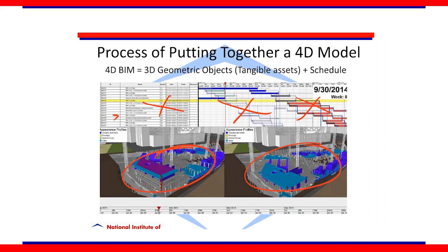So the way it is done is, if you have an item here, for example, let's say we're pouring foundation, sector A. What they do is they connect this particular line item into the sets of the 3D. So you technically click on this, basically whatever the columns and footings are linked to that particular line item, and you say link. So you keep doing that.